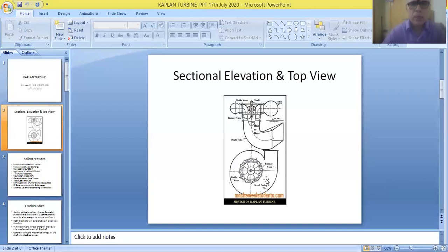You can see the disc here. So a rotating disc is mounted on the shaft of the turbine. So that is called as a runner. And in the case of KAPLAN turbine, 4 to 8 blades, around 8 blades are fitted around the periphery of the runner. That means in between the inner diameter and outer diameter of the runner. So they are called as runner blades.